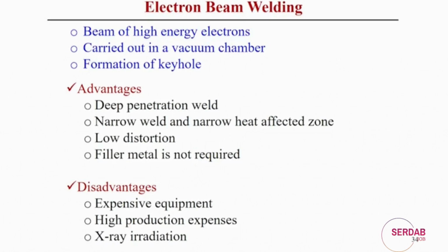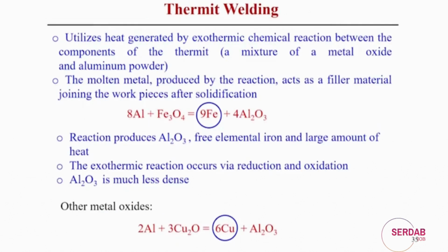That means electron beam welding can be used as compared to other welding processes, but during electron beam welding, secondary scattering, that means X-ray irradiation, also happens during the process. So, that needs protection during the welding process. Apart from this disadvantage, in general electron beam welding is normally preferred when there is a requirement of high precision, by compromising on the cost of this welding process.